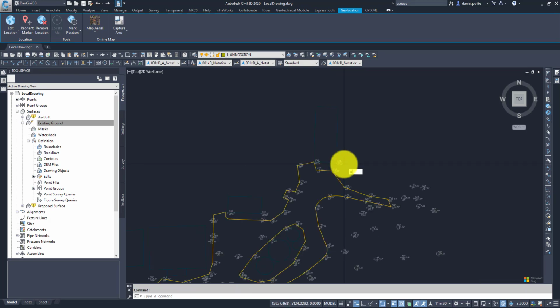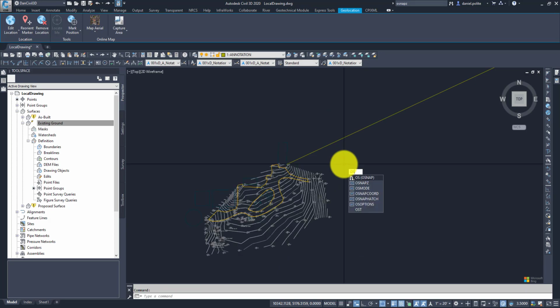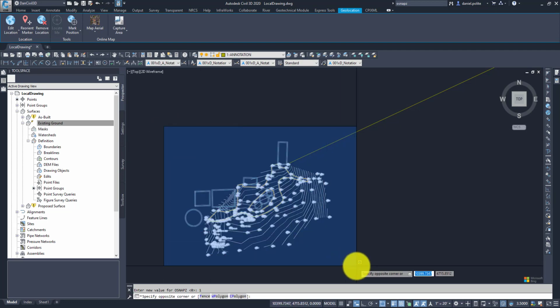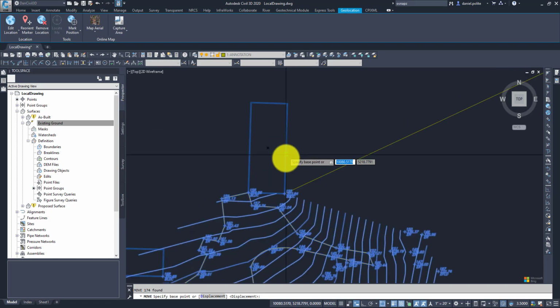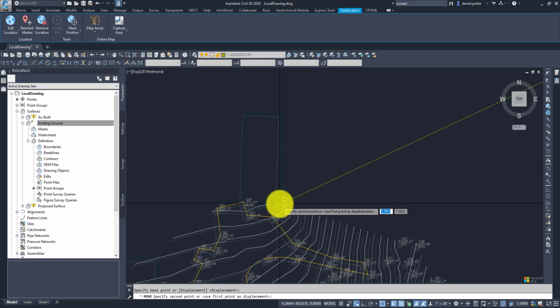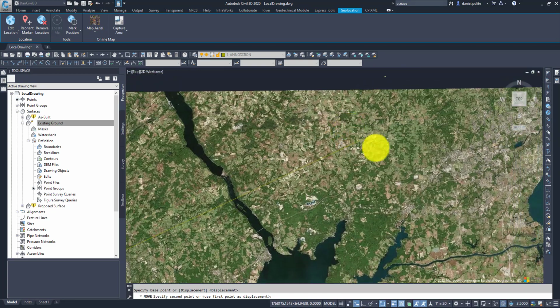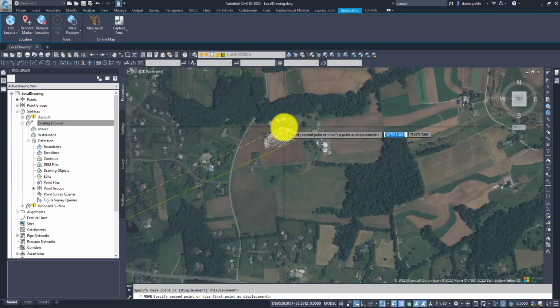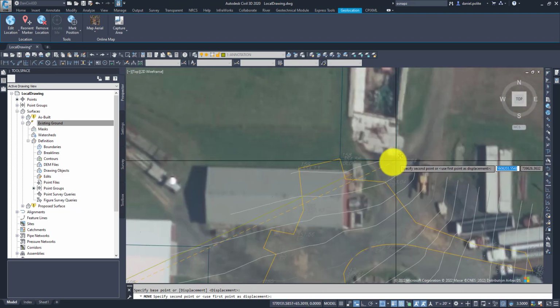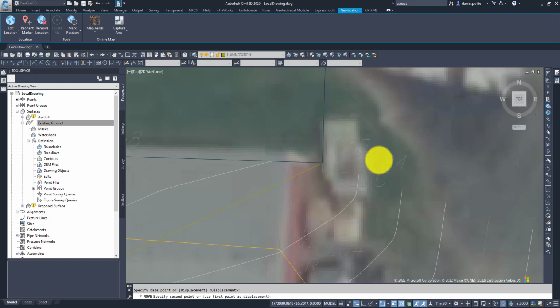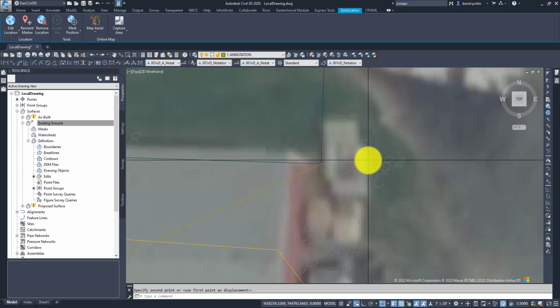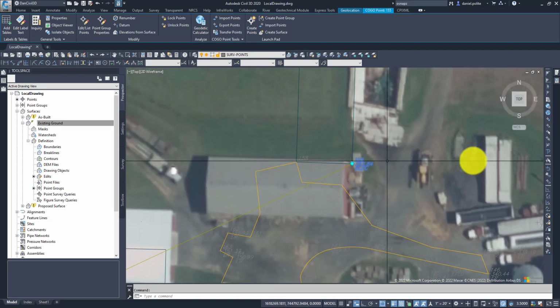So we'll undo that, turning that O-snap Z to 1, move again, just select that corner of the building, we can zoom out, don't have to go along that specific polyline. It's just nice to draw that polyline in regardless, just so you know where you're going, and then you can snap to it. And then 350, 384, it stayed the same elevation as it was originally.